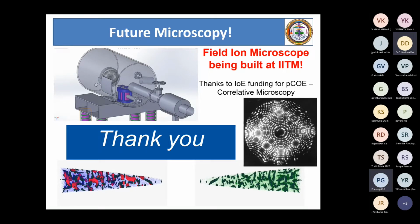Okay, so anything on a nanometer scale, as I showed in the 2 examples of clustering, cannot be considered as stable forever. It is in a metastable state, right? So when we apply thermal energy for a given time, these clusters will try to coagulate or coarsen, so that the smaller ones disappear and bigger ones tend to coarsen to reduce the free energy of the interface. So this is bound to happen. The only difference is, for any material that is produced in a non-equilibrium way, these kinds of nanoscale structures will exist, but they will exist only as long as there is not enough energy available for them to coarsen. When energy is available, then they are going to coarsen.